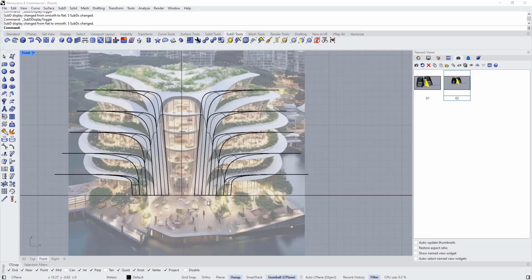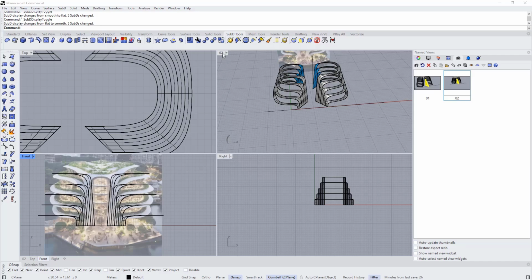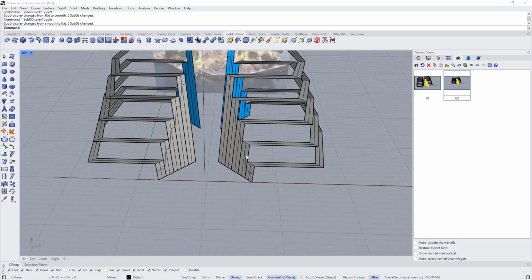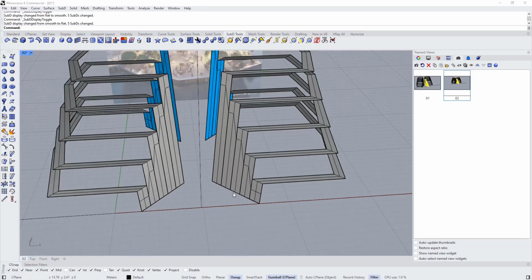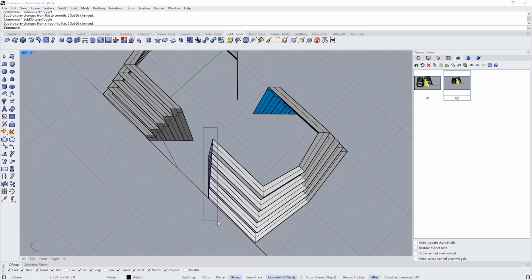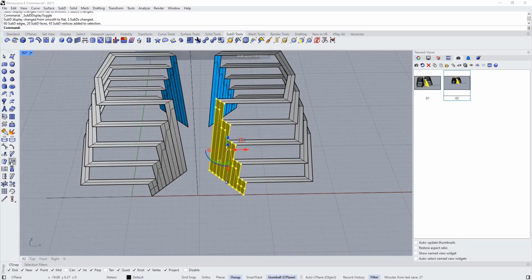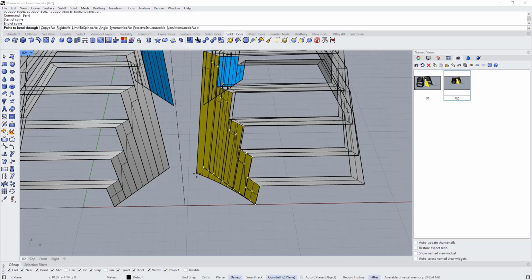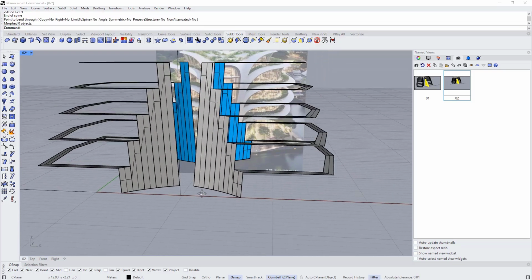And another thing, as you can see, there is some kind of curve here. Let's double click to minimize the view, double click to go to the object. Right now it is just flat. So to create this curve, we are going to use bend. So again, let's adjust the view to be something maybe like this. Hold Control Shift, select all the faces. Let's choose bend. Select this point, and start adjusting something a little bit like this.